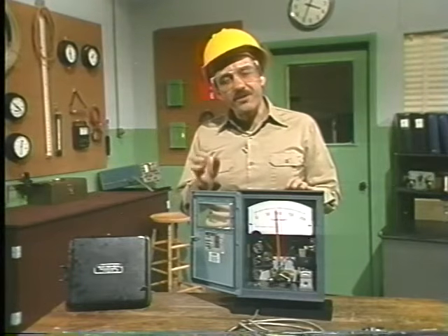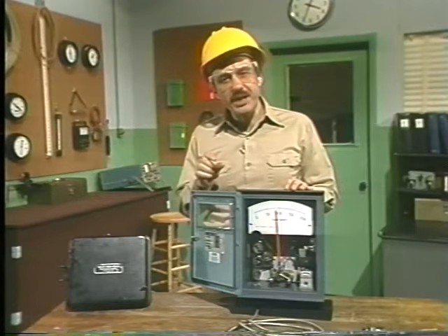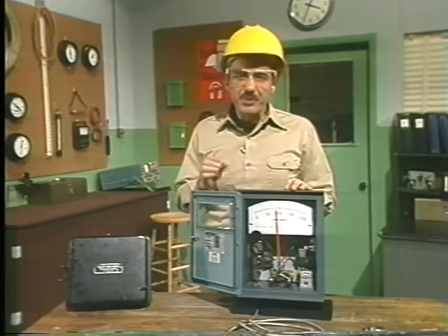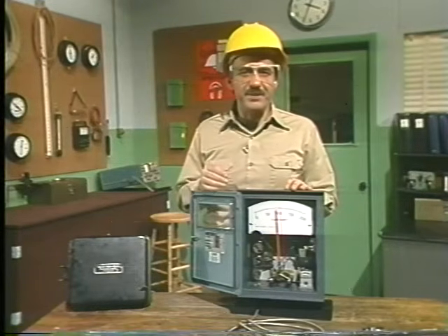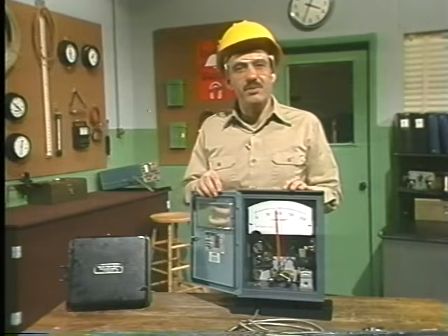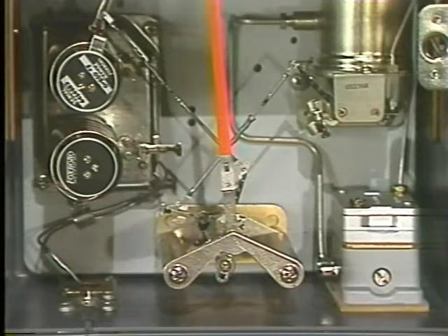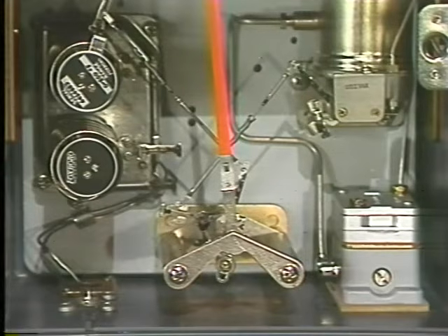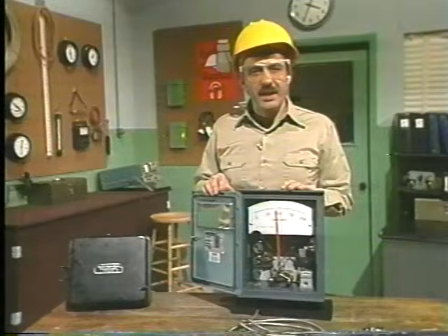Now remember that the function of an error detector is to convert a small mechanical motion into a proportional back pressure. And each time a flapper is repositioned, it is moved as a result of a change in an input mechanism, such as a Bourdon tube, bellows, or diaphragm. As we saw, in this temperature transmitter, the error detector is a flapper nozzle. The flapper is connected by a series of links and levers to a Bourdon tube input mechanism.